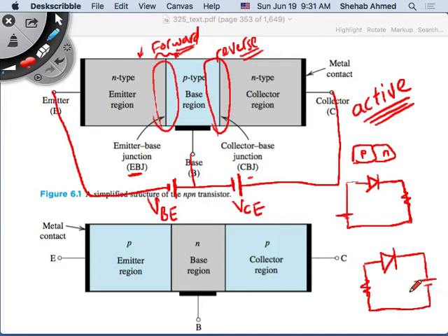Right? This is VCE, correct? And it's reverse biased. If I put VCE at 0, is the diode reverse biased or forward biased? Why? What do you need to do to make the diode conduct current? Remember your diodes chapter. What do you need to do? More, but how much more?